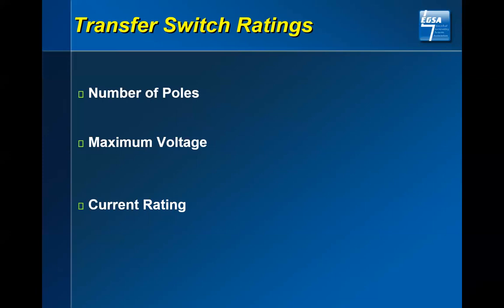Pushing that point just a minute, sometimes you'll see in the case of some buildings that it may have an 800 amp service coming in on the normal side. As long as everything is normal, in this case, all elevators are in operation. However, because of the size of the generator set, I'm only going to supply 600 amps: 800 amp from the utility, 600 amp from my emergency generator. I must provide a switch that is equal to whatever the larger circuit breaker is. I can put a smaller breaker, but I cannot put a smaller switch. Just a point of comment.